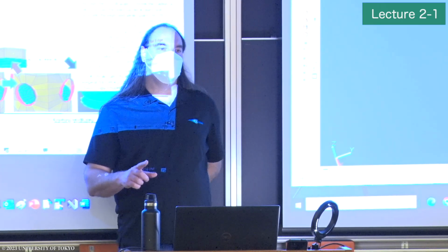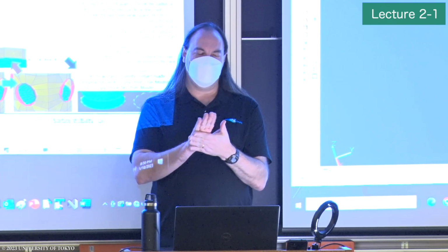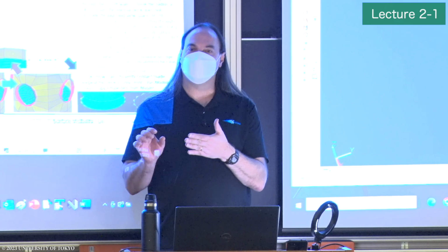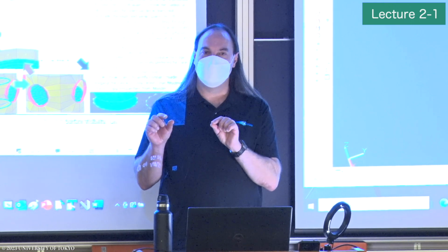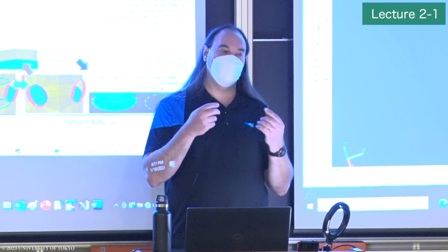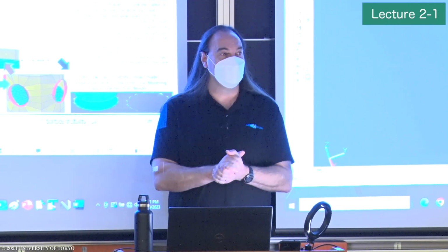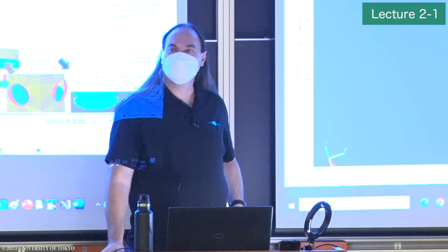Before we jump into Q&A, there was one thing I did want to note that's a subtlety. If you have a rectangle or any other surface and you have a length or a parameter of its geometry that's defined by a symbol, then you can't use the grips to extend it. So if I had said that this rectangle was x max long, I'm not allowed to use the grips to extend it. It will always remain x max. So if you are using symbols to define your geometry, that might limit your use of grips, as we demonstrated earlier with the CubeSat model to be able to extend surfaces. So otherwise, are there some questions? I'd love to hear them.